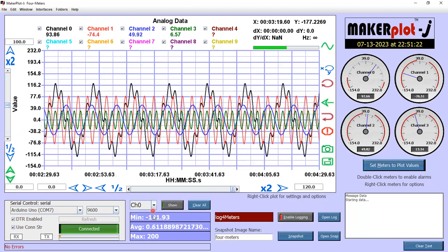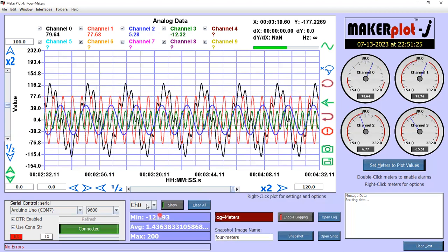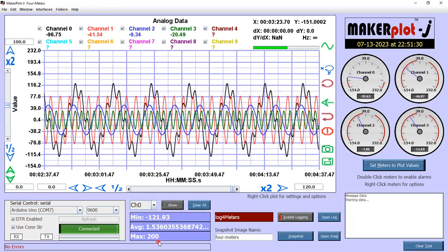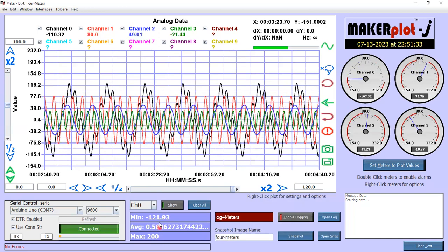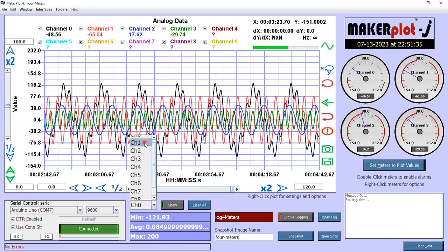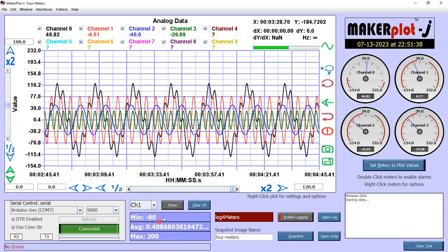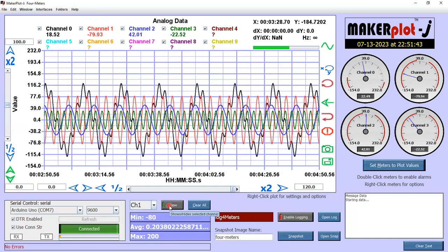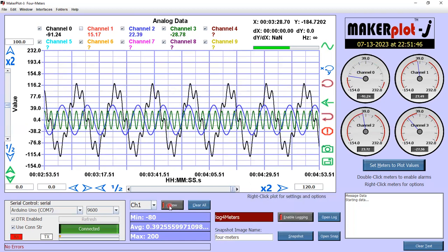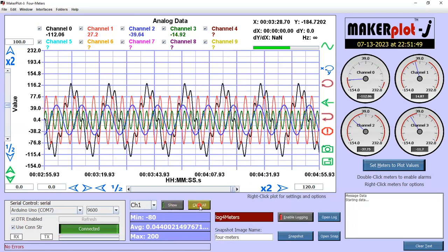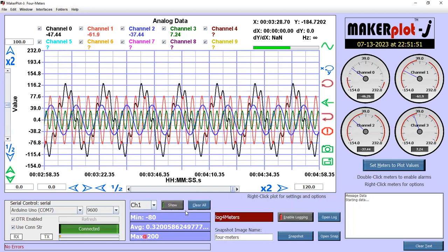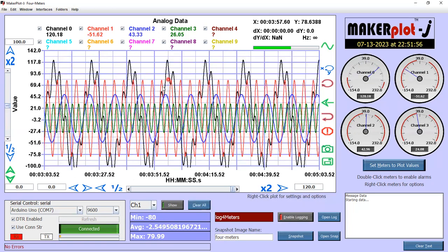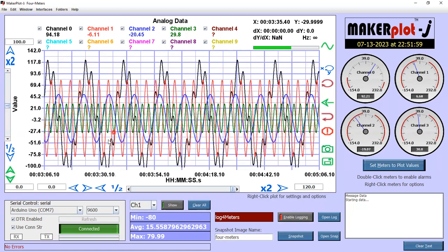Also on the screen, we're seeing the minimum for channel 0 listed down here, plus the maximum value it reached, and that was the 200 we typed in earlier. It's set that as being the maximum. Or we can select a different channel to monitor, such as channel 1. From here, if I want to, I could turn off channel 1 and not show it, or show it. Or I can clear the min-max average here, which will clear the values it's using for auto scaling right now.